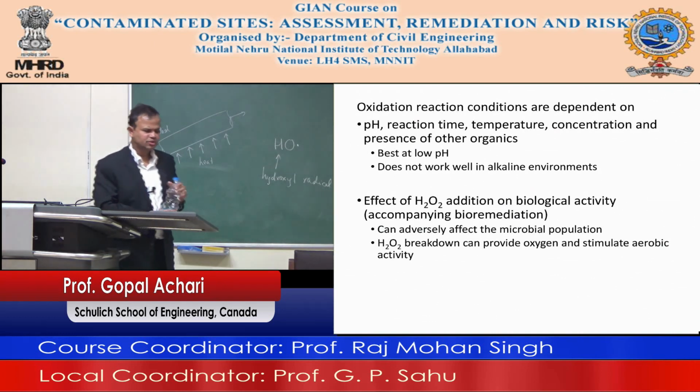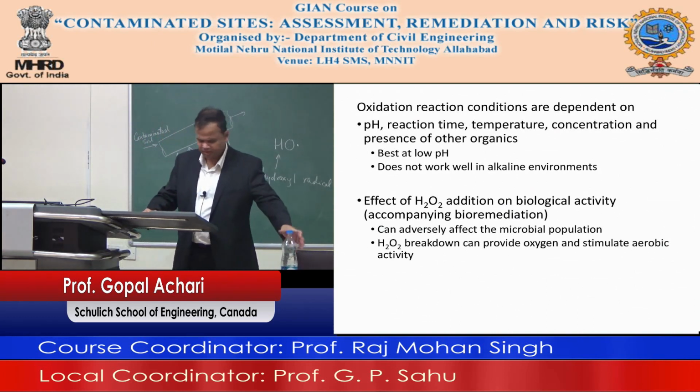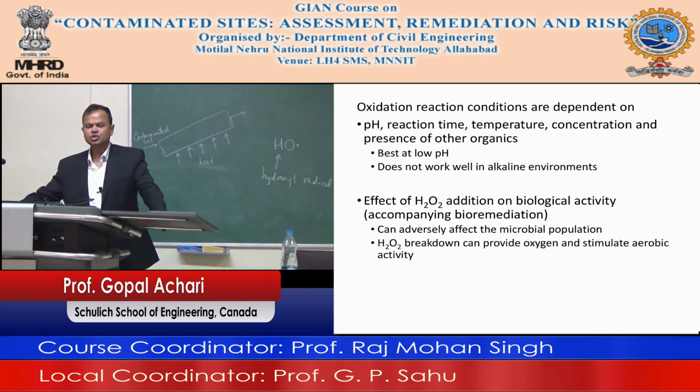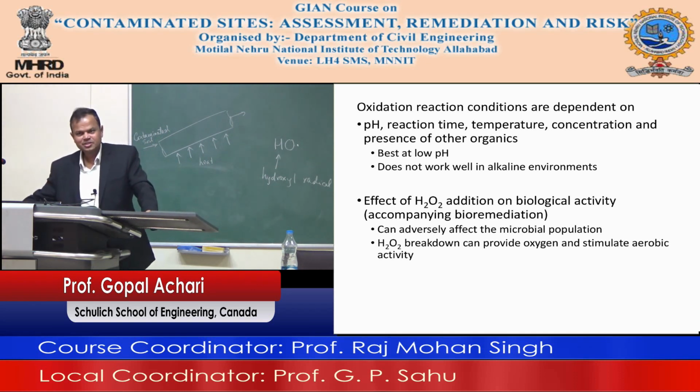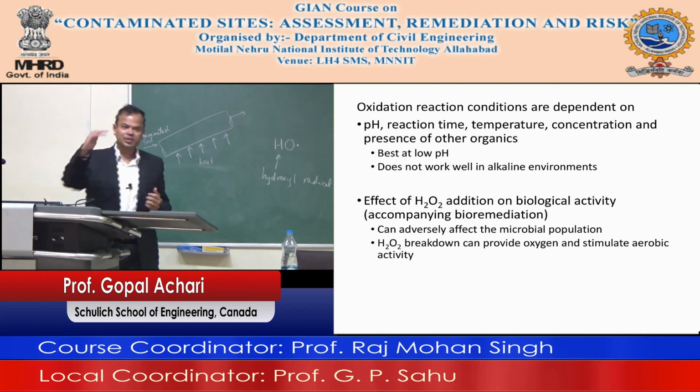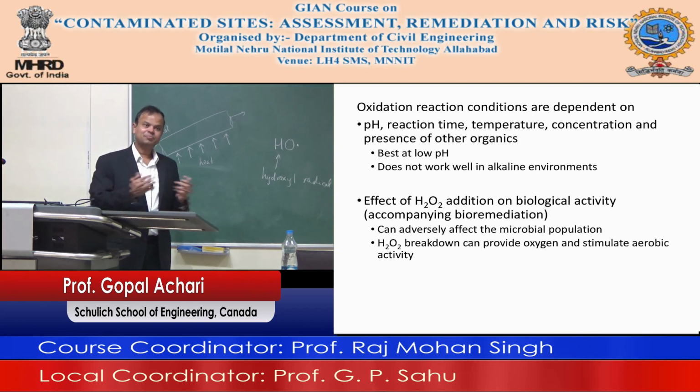You have some acidic soils which have lower pH, but by and large, the thing is, soil also has what is known as a buffering capacity. If you add something to lower its pH, it will not happen, because some of the carbonates and so on that are present in soil will break down to prevent the pH from going down. It's hard to get the pH of soil down. And the problem is, iron precipitates out at the pH we talked about, so it is not as effective as it would be if you can get the pH down to 3, which is not feasible.